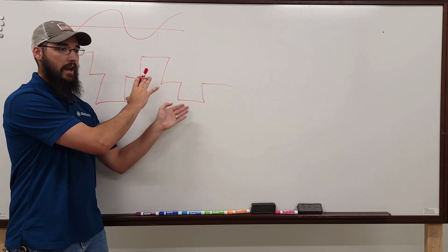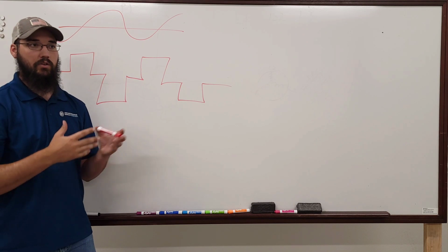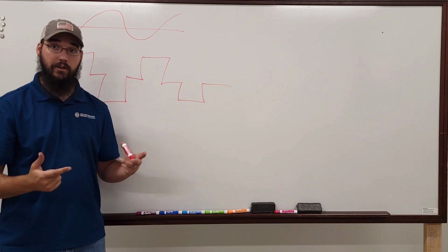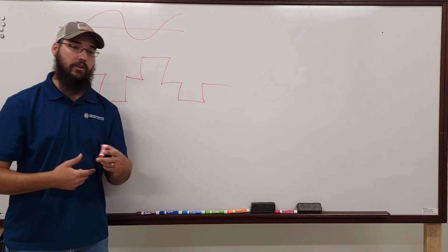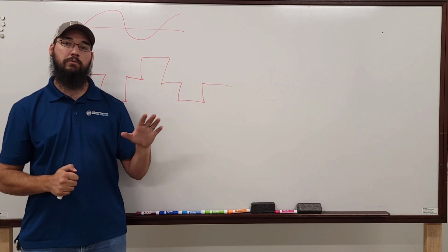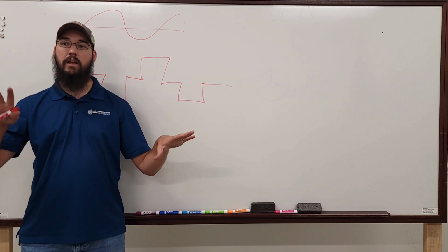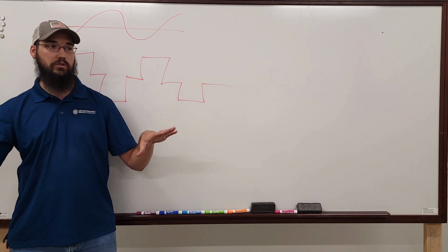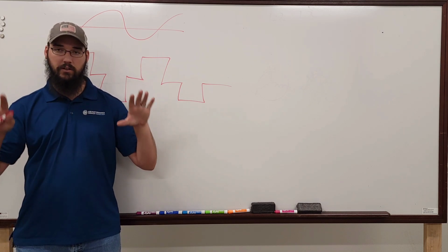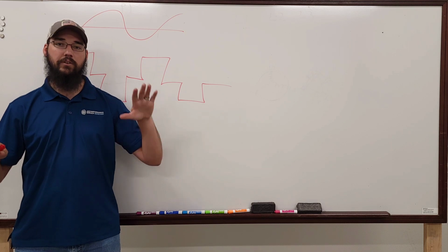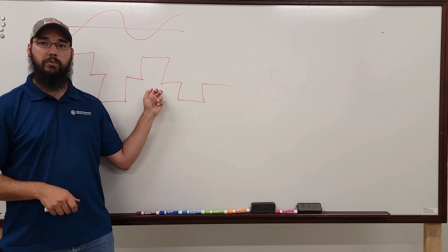This does not create a true pure harmonic wave internally in the stator, and you can hear it. Once you get familiar with it, you can hear the difference in the motor running between a VFD driven motor and a straight, hard starter motor. There's a literal sound difference, and you can hear the pitch of the harmonics off of this pulse width modulated wave.